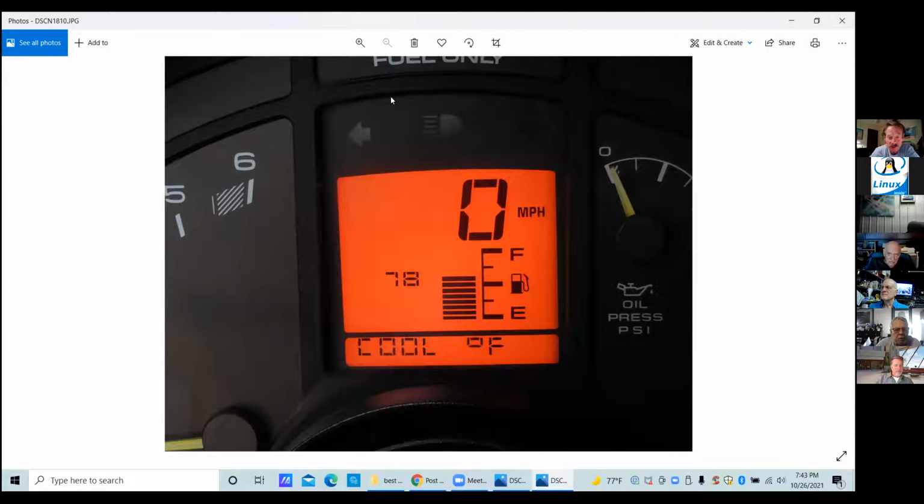So then I took the whole thing apart again, which I really didn't mind doing because I had a bulb that didn't work. The high beam bulb didn't work. I tested it with voltage and an ohm meter, so that one got past me. When I took it out, I retested it, and the bulb was intermittent because I got a good reading. The bulb itself, with the leads coming out, is in a plastic holder, like a lot of the bulbs of today. And you just put the plastic holder in the circuit board and turn it a quarter turn, and it locks in, and it's got contacts.